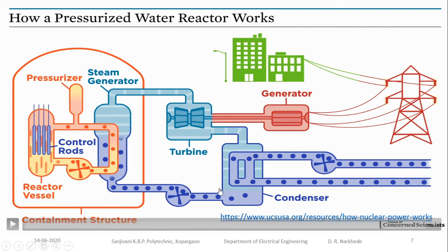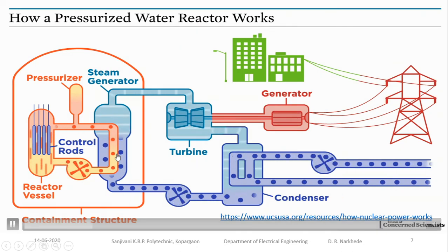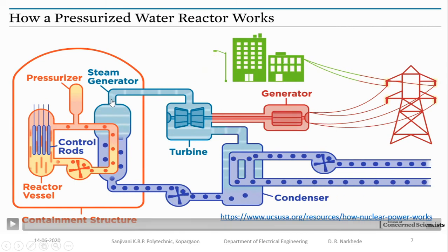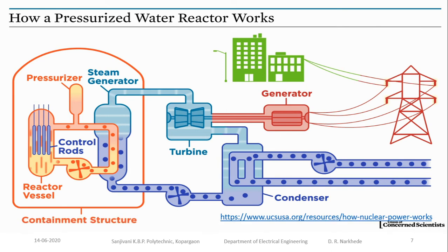In the heat exchanger, when you pass the water through it, the water will extract the heat of this pressurized water, and then its temperature increases to 250 degrees centigrade. This steam is of poor quality, at a temperature around 250 degrees centigrade and a pressure of 42 kilogram per square centimeter. The steam is condensed in the condenser and the condensate is returned to the heat exchanger, forming a closed circuit.